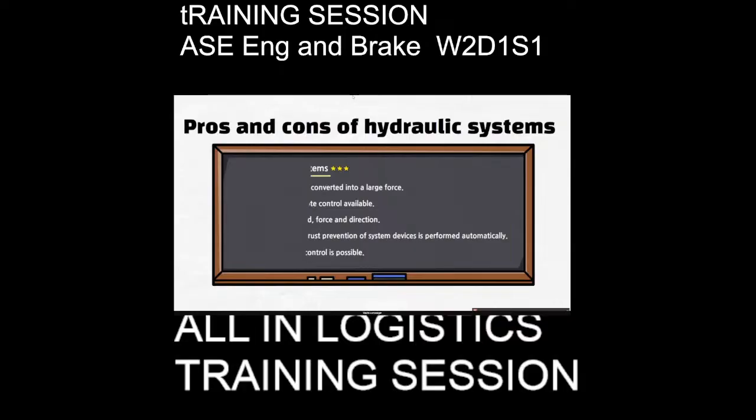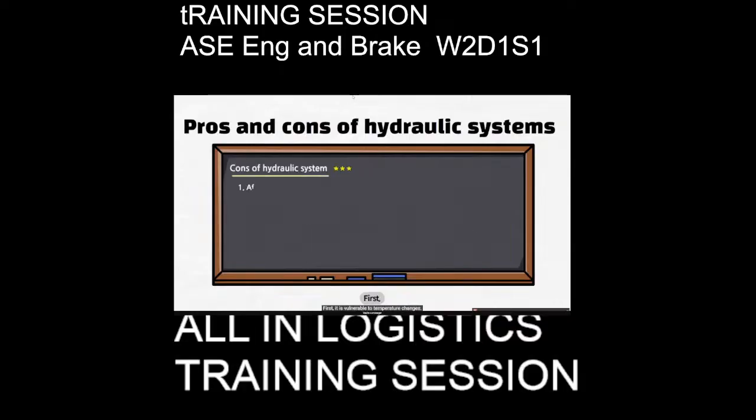Disadvantages of the hydraulic system are as follows. First, it is vulnerable to temperature changes. Viscosity decreased due to temperature changes may affect unit operation. Third, there is a risk of ignition. The working fluid is oil in the first place, so operators must take caution and prevent the oil from being ignited. Oil circulation may form small bubbles, and failure to remove such bubbles properly may result in poor operation of the actuator.